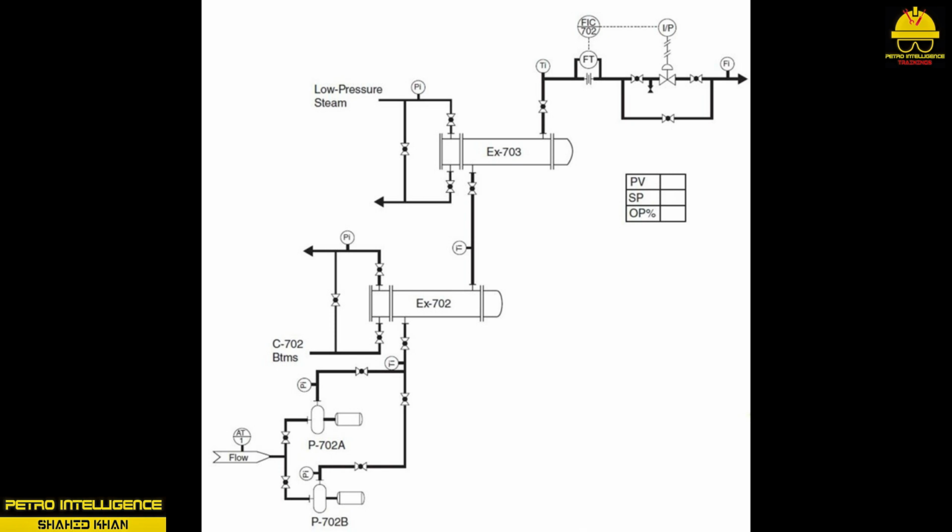The hot pentane flowing from the bottom of C702 is used as the heating medium for X702. This process allows heat to be transferred from the pentane to the butane-pentane feedstock mixture. Correct valve lineup into and out of the exchangers is an important feature of operating the preheat system. A product analyzer continuously monitors feed composition.